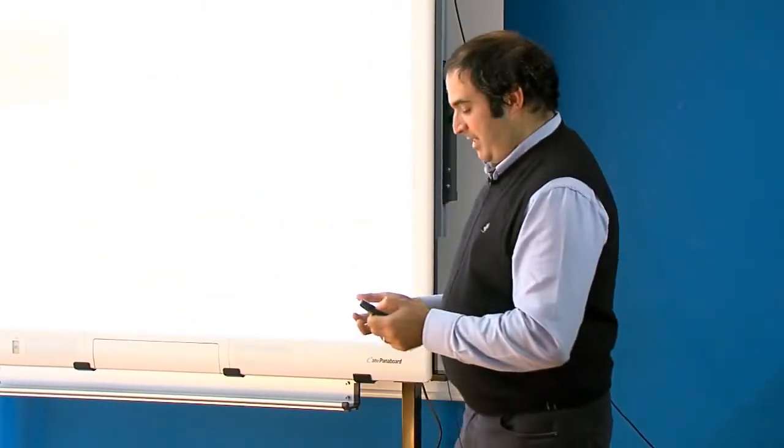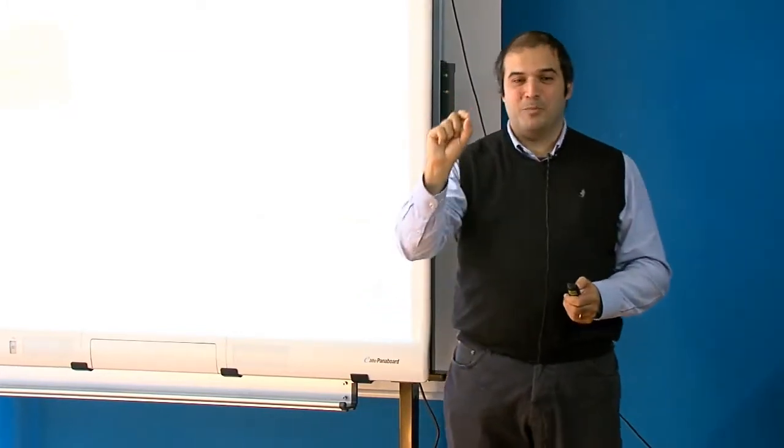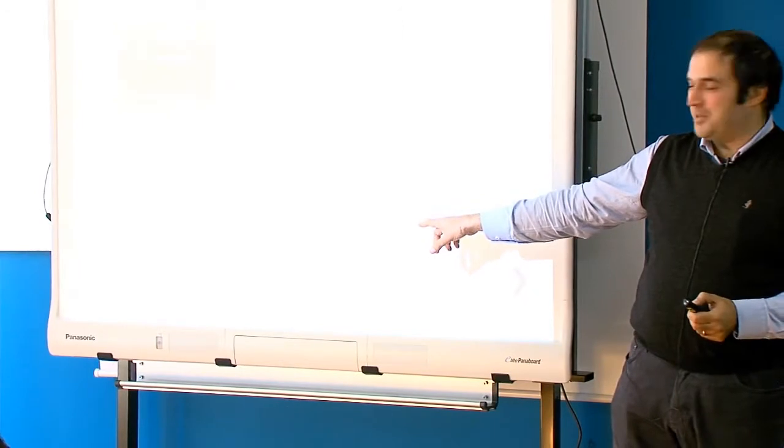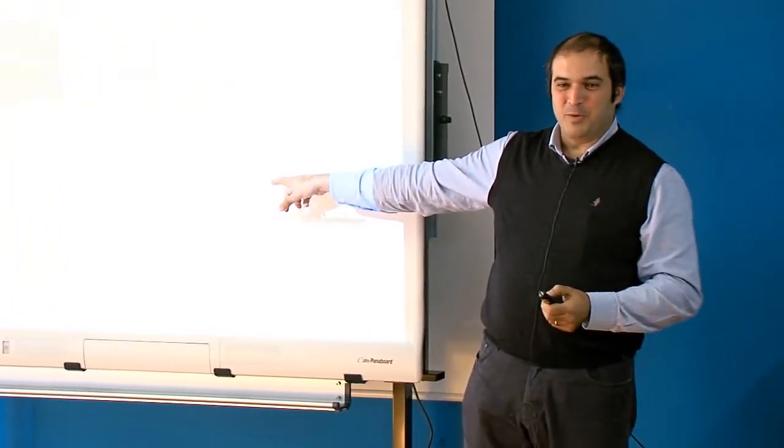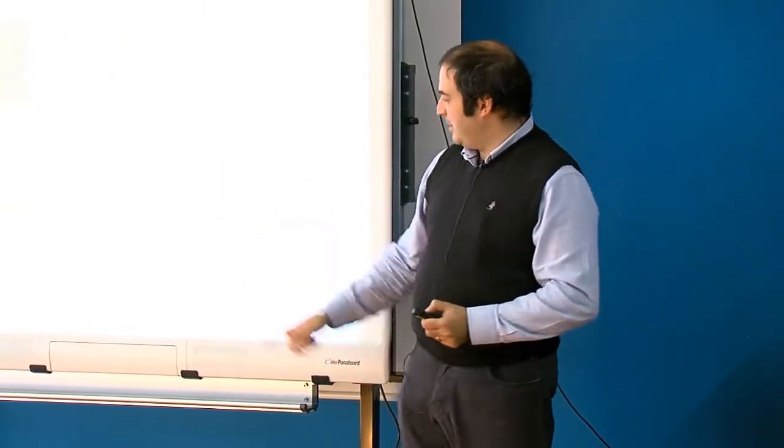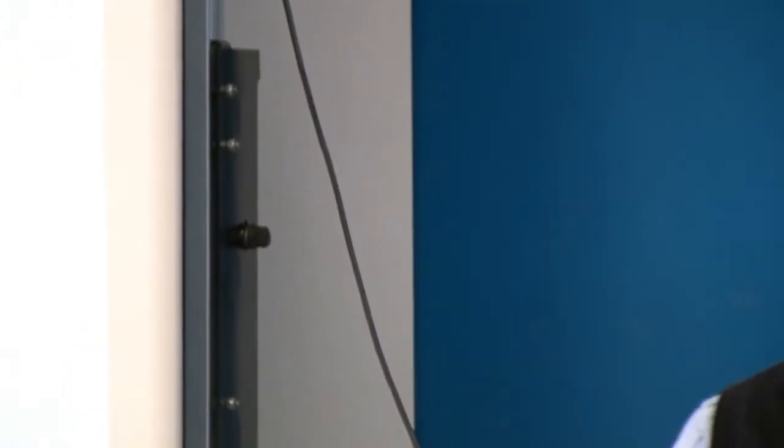So how can I measure this? Because if you go to the lab and extract your model with this, what is going to happen? It gives you bad results, which means that you build a device with this model, you give it to your customer, and you have higher distortion, and the customer sends the instrument back, saying no, this is not working, it is not fitting the mask. So my question is, we have similar power spectral density and similar integrated power. If you integrate the power, you have the same power, the power spectral density is the same, but you have completely different spectral regrowth. That is, you have completely different behavior of your system.